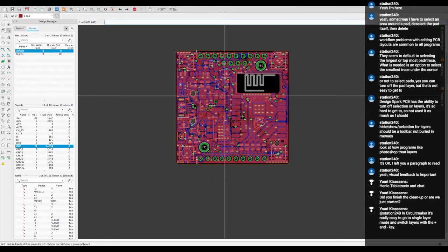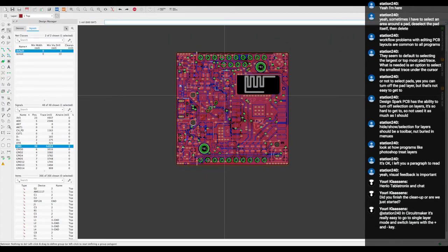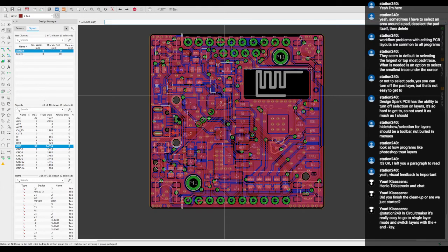So that's what I've been working on. Every time I went to submit this, I kept deciding, oh, I'm gonna add one more thing, so I didn't add a lot. I mostly just added some fixes. But when you got to squeeze two resistors into something, you got to really redo the whole board because it was way too tight. Then I had to fix my ground and make sure my ground was a little better.